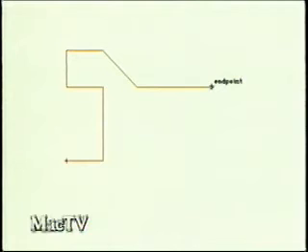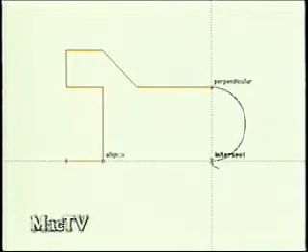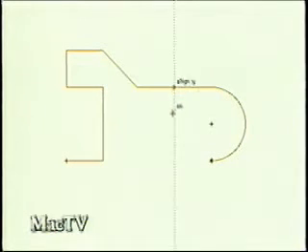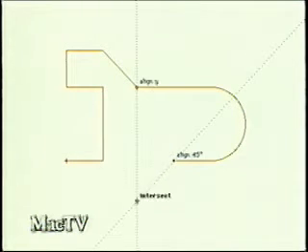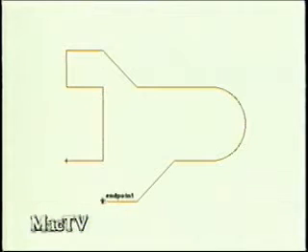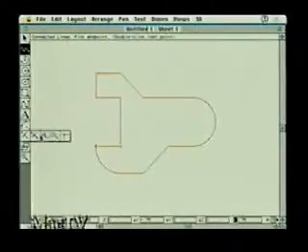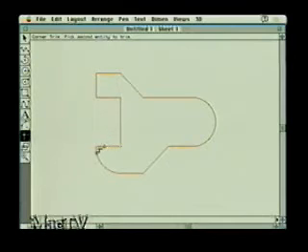Oh, that's easy enough. And then I can hold the Option key and temporarily get an arc tool, which happens constantly when you're doing a design. I can slide right down and hit that intersect. Slide right across. Now I can make this line end right below the midpoint of this line just by going up, touching the midpoint, coming down that line, and there's that intersect. I can slide down this line to that intersect. So these alignments, this snapping, all of this happens automatically, and it makes the whole process real nice to work with. Now I'm going to join these two lines together to make sure they're exactly right with my corner trim tool, and two clicks, and I've got it exactly right.